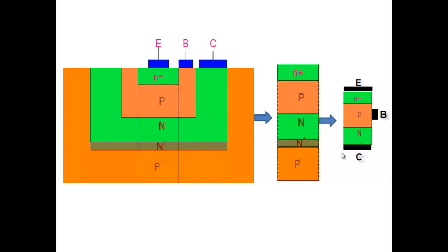But then we say there's a contact here. And for the base, we know that the base provides a contact here through this region, but we simply draw and put a contact here. So understand what this contact means. It doesn't mean that I have something stuck to the side. It means that the contact is over here, right? And this region plus all this P-type region is what we are representing here. And similarly, for the N plus, we put a contact here. So this is how we arrive at our simplified one-dimensional view of an NPN transistor.